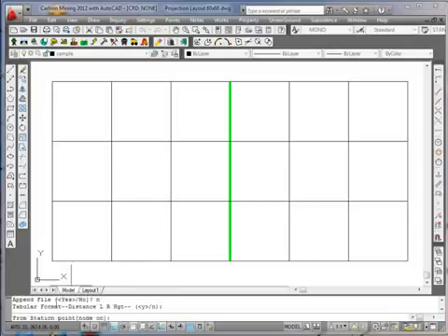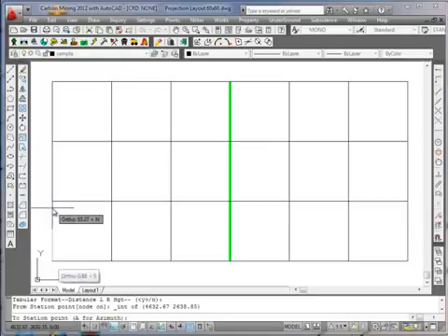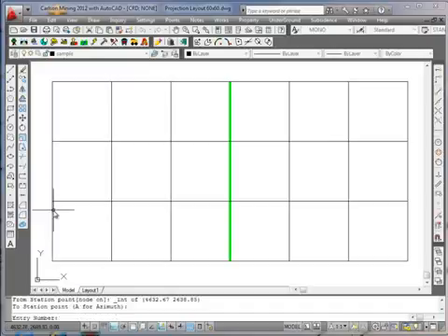And now we're prompted from station point, a node on, and I'm going to set the snap, in this case, to the intersection, and indicate the direction. I'm in ortho mode. I'm just going to pick up here for the direction. I could type in the azimuth that I wanted to lay out this projection on. The entry number will be 1.